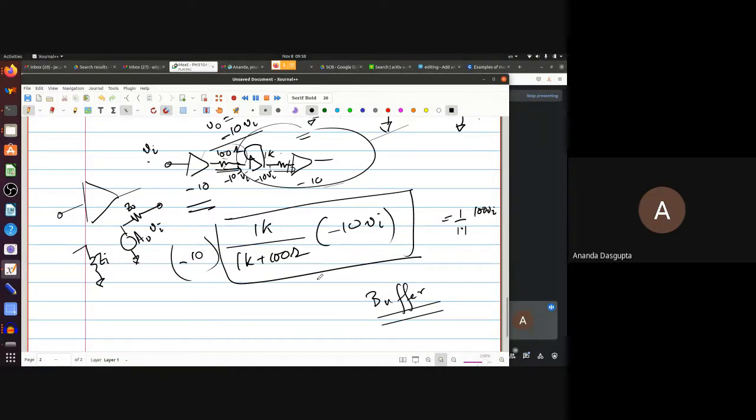And there, the word operational actually means mathematical operations, as we discussed: integration, differentiation, solving differential equations, etc., with op-amps. But if you are going to use them, especially in analog computers, that is, computers made of op-amps meant to solve specific problems, you use them in situations where you need high precision as well as very rapid response.